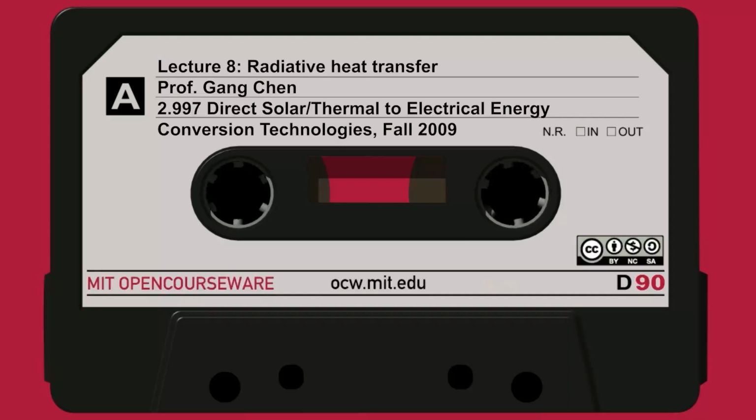A coal plant is about 40%, and if you combine a gas turbine and a combined cycle, combine a gas turbine with a steam turbine, so you burn fuels, you generate hot gas which drives a gas turbine, and the exhaust generates steam to drive a steam turbine. That combined is about 60%.